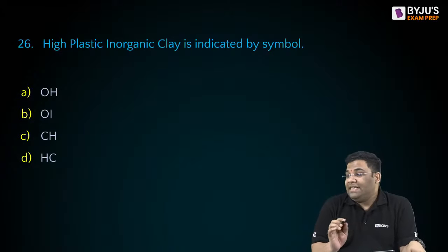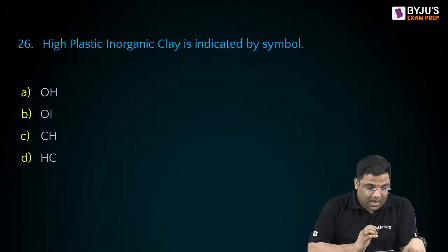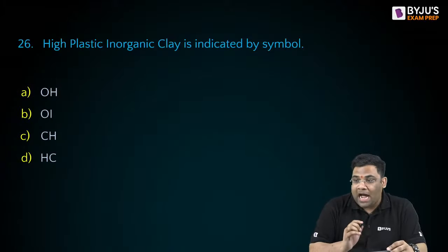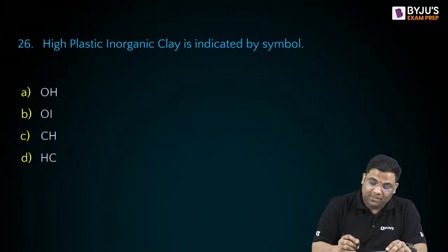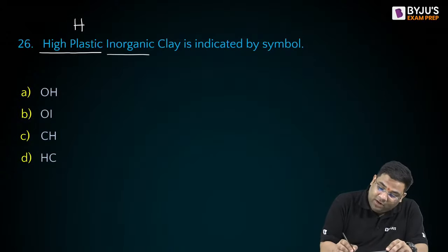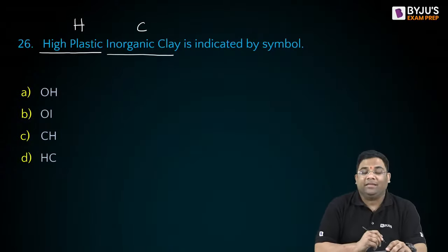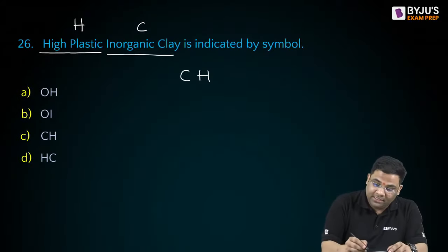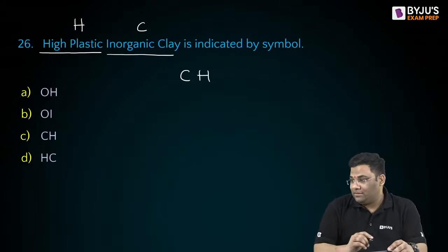High plastic inorganic clay. What do we call that? See, high plastic means H. Inorganic clay means what? Your C. So CH. We write it reversed, right?